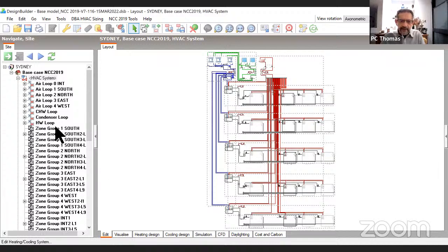And in the chilled water, we have a supply side. So there are 3 chillers, 1 low load chiller, 2 main chillers. Each one has got a pump. There's a supply header, there's a return header, there's a controller, okay? And each of those things you can look at. And then that supplies chilled water to all the cooling coils in all the air handlers.